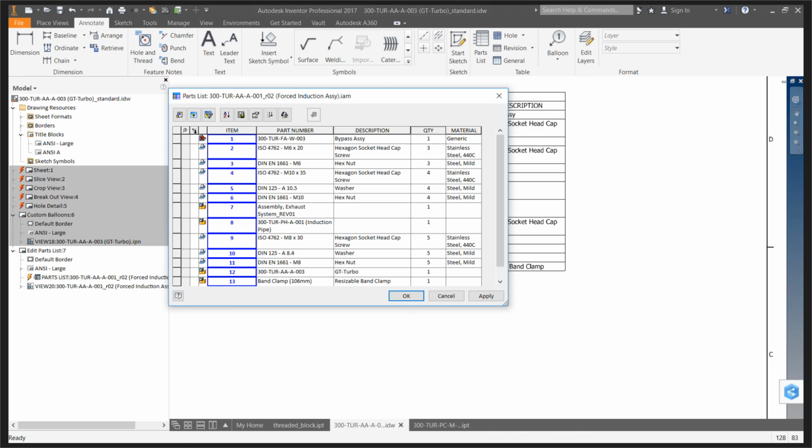Yep. And note for those of you who are using things like Frame Generator, that quantity field is going to be cut length. But if you want to change that to the actual quantity of that part, there are ways to do that. You can remap the properties. And sometimes people use item quantity. And actually, Nigel, you bring up a great point. I have a lot of customers that use Frame Generator to develop parts, and what they're after is how many 10-foot pieces of steel do I need?